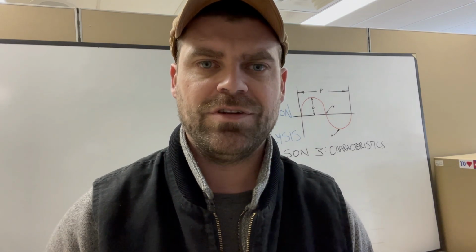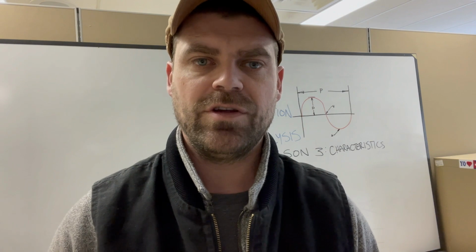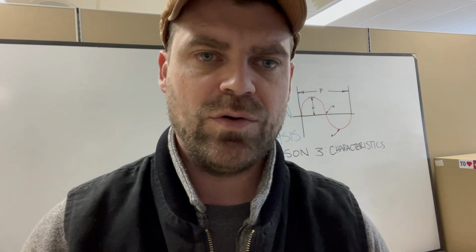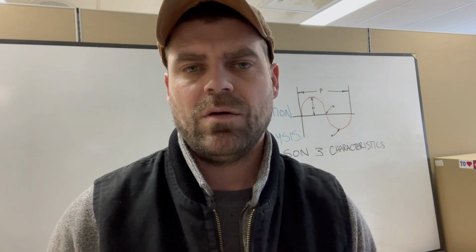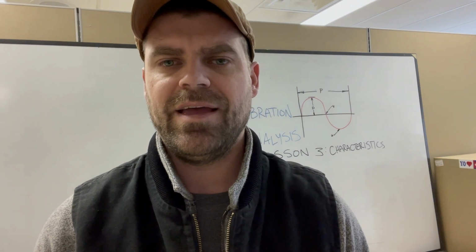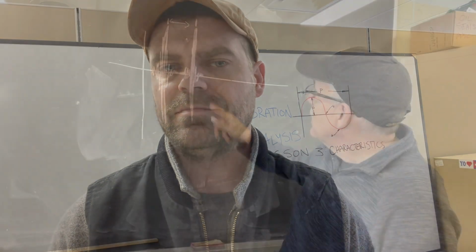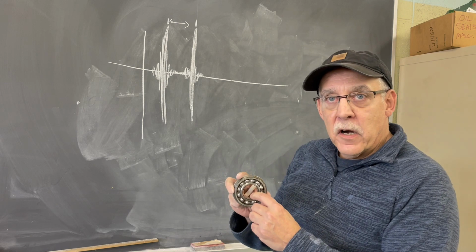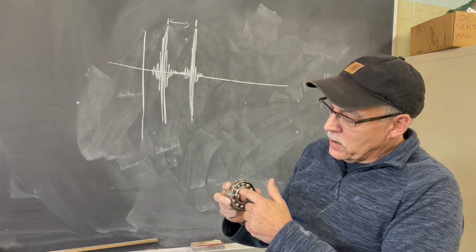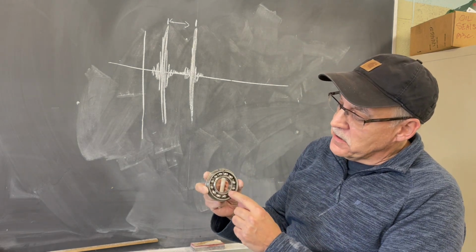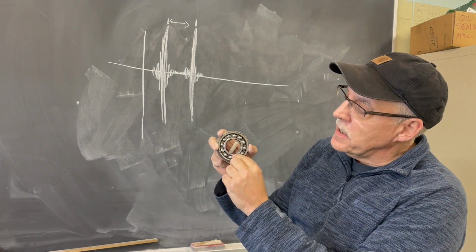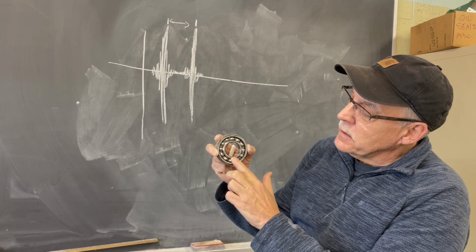Our vibration data collector and software can also distill that waveform into individual frequencies. If we know that data, we can look at diagnosing even more faults. What are the different types of faults, and what are they a symptom or a sign of? If I had an inner race defect on the bearing, if you think about it here, what happens with this? If we have a defect on the inner race and the outer race is clamped, what happens to that defect on the inner race?